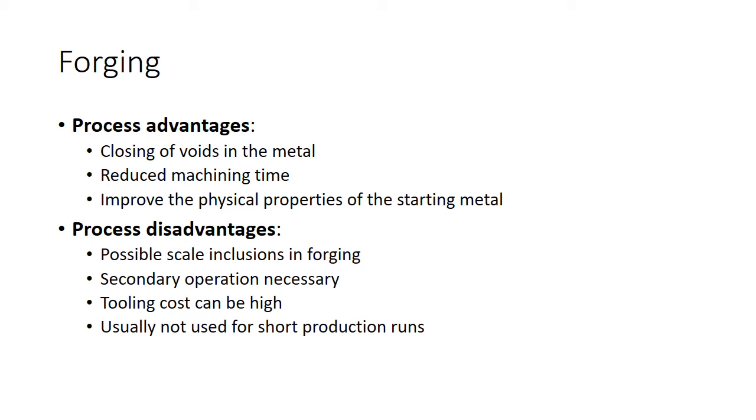Disadvantage is you got that scale, so it's got to be cleaned off. And it's a secondary operation. You're going to have to do some machining to it to make it fit, or at least some polishing to get any scale off. And it can be fairly expensive to get all the tooling for mass production right.